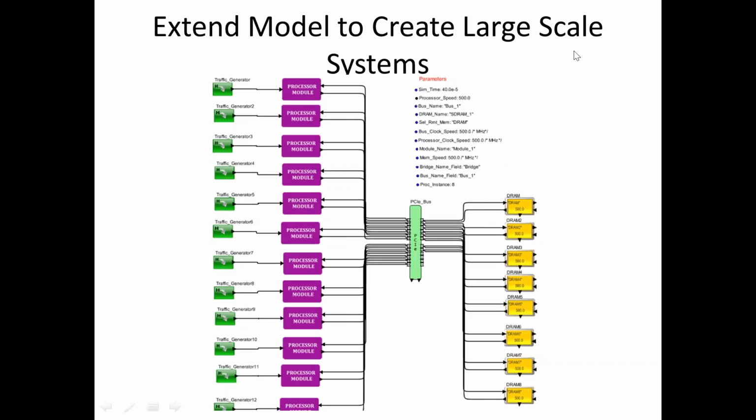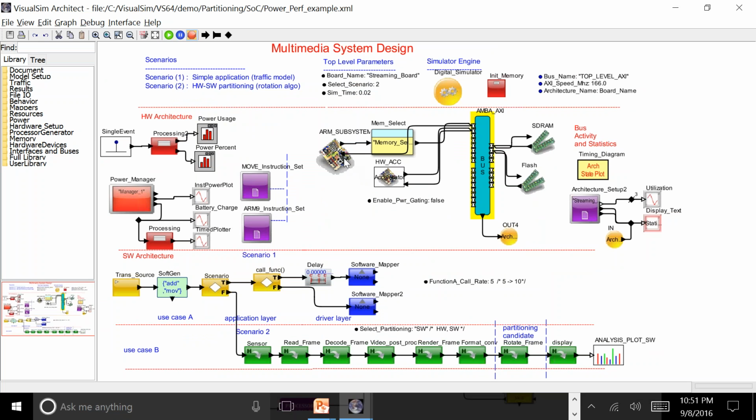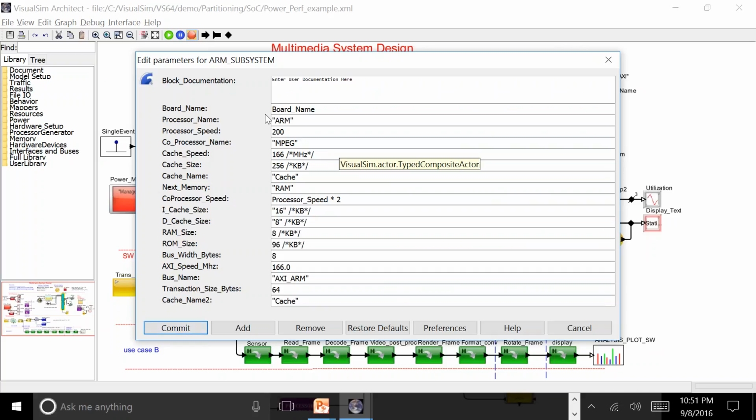Of course, at top level, you have all these parameters. What this allows you to do is take those blocks you created as hierarchical, put them into your user library, and then instantiate them multiple times within your system. To give you an idea of how that works, say I go into this one over here, and I have this particular component. I'm just going to put that right over here.